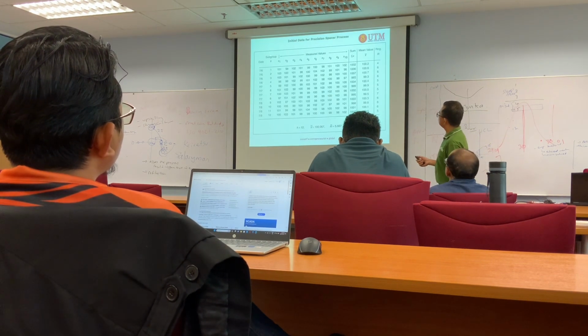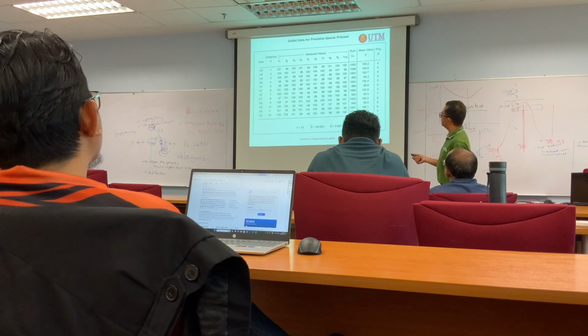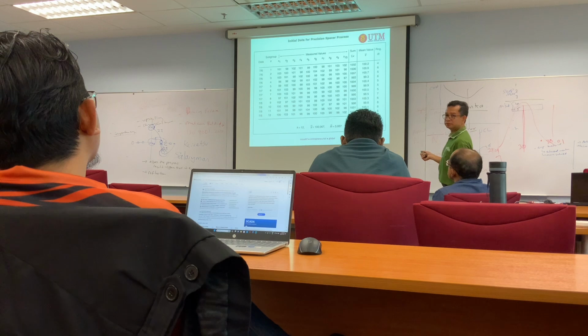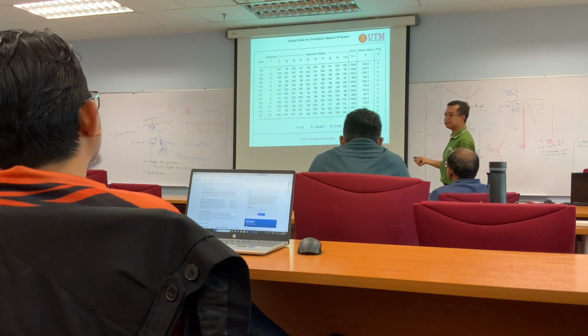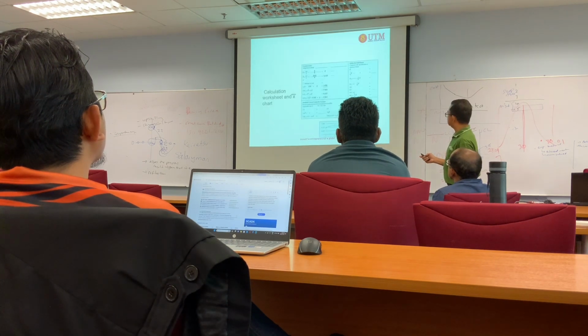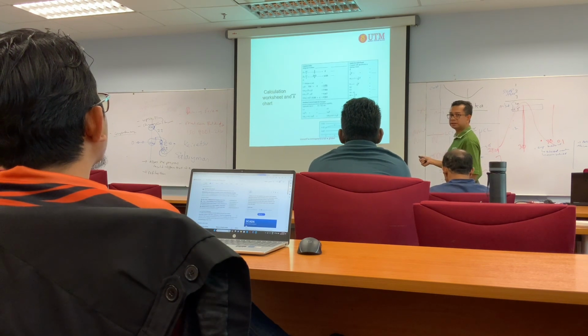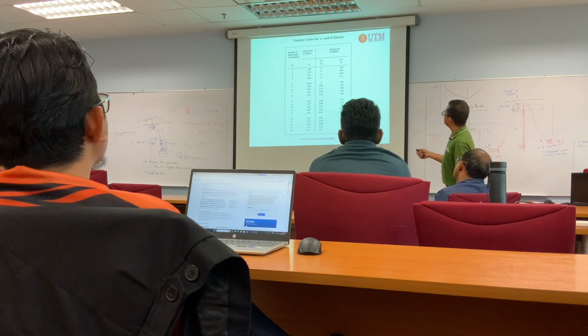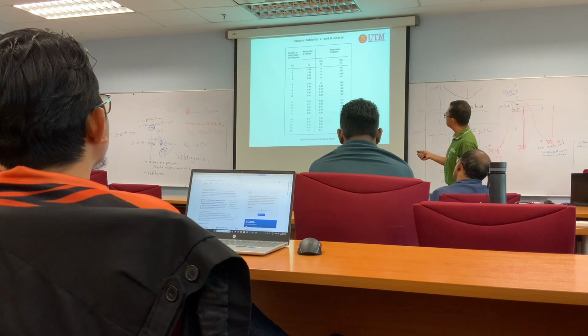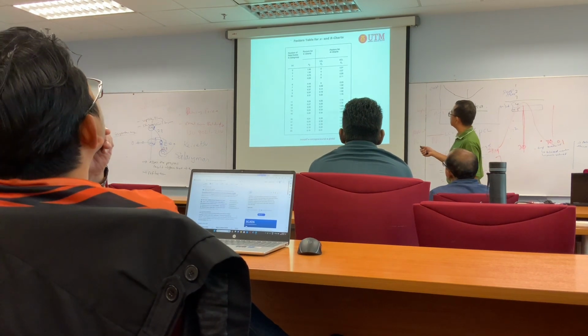So for this case, if we have 10 samples for each subgroup, this is subgroup, morning, afternoon and evening, maybe night is one. They take 10 samples, then they got the X bar and range. I think you know already how to get this X double bar and R bar. So when we have 10 samples for each subgroup, this table we only have until 6. We cannot use this. We must use the big table like this. 10, so D3 is 0.31.